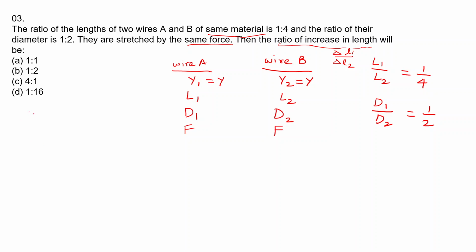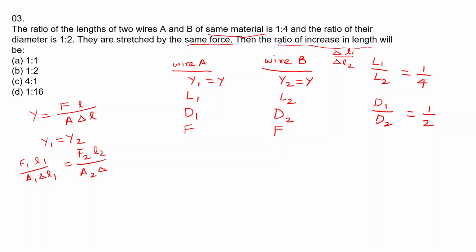So again, what is the formula of Young's modulus? Force per unit area, and yes, this is the formula. Now the Young's modulus for both the materials is the same, right? That means Y1 is equal to Y2. That means F1 L1 divided by A1 delta L1 is equal to F2 L2 divided by A2 delta L2.